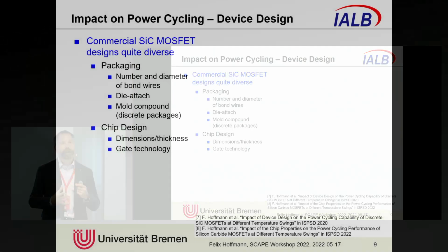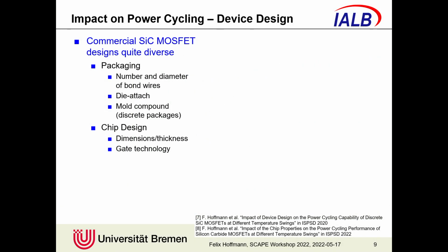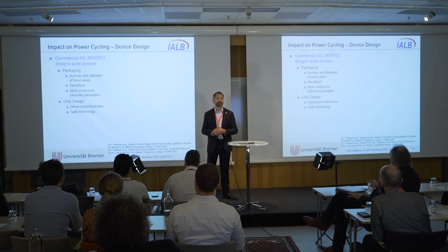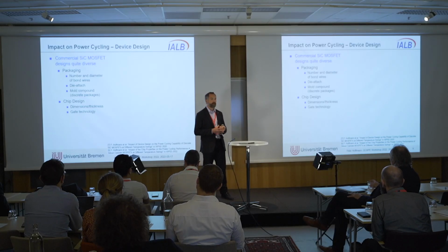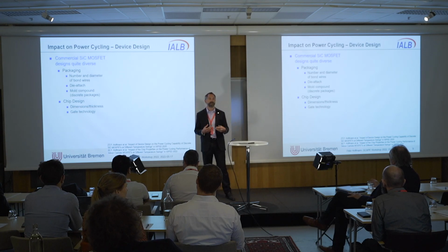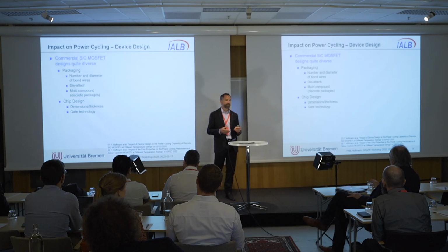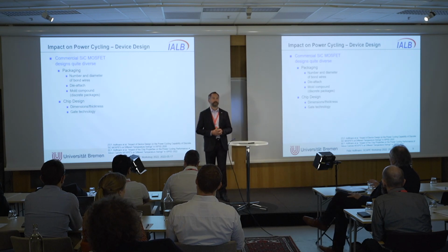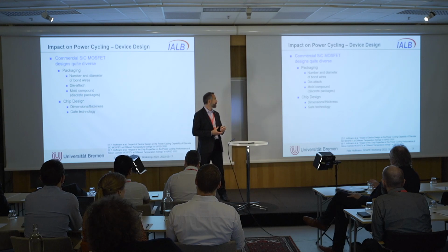So let's now discuss the impact of the device design. As I said previously, we have significantly different device designs on the market, and particularly discrete devices differ in number and diameter of bond wires. Also, the mold compound is different, and also we have differences in the chip design, which also include the chip thickness, as some manufacturers thin their chips, and also differences in gate technology.